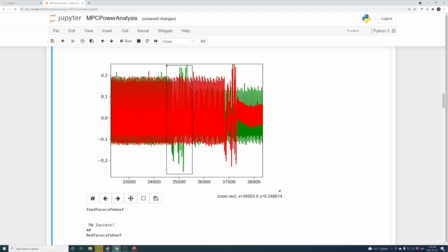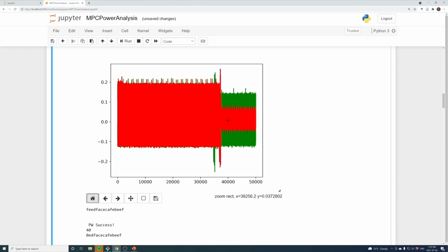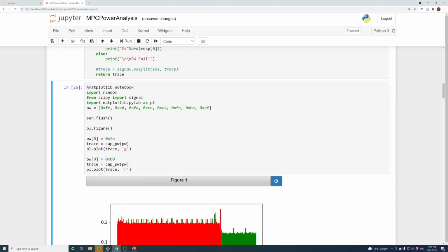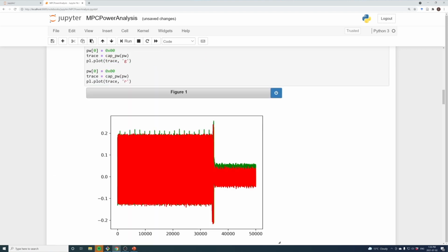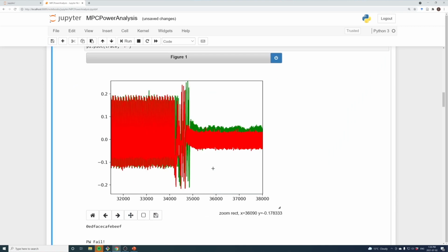What we're seeing here is that the red line is continuing the comparison or something, and then eventually we see it split down into this smaller loop here. And what's this smaller consumption? I actually know that the device just waits for a watchdog reset when the password's wrong. So that's what you're seeing right there: the device waiting. Just as a reference, if I send both of these the exact same incorrect password, you can see they don't match up perfectly, so there's some jitter here.